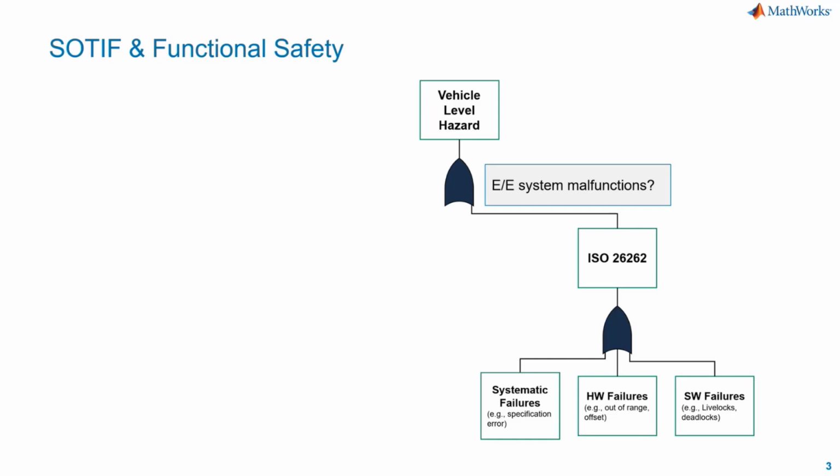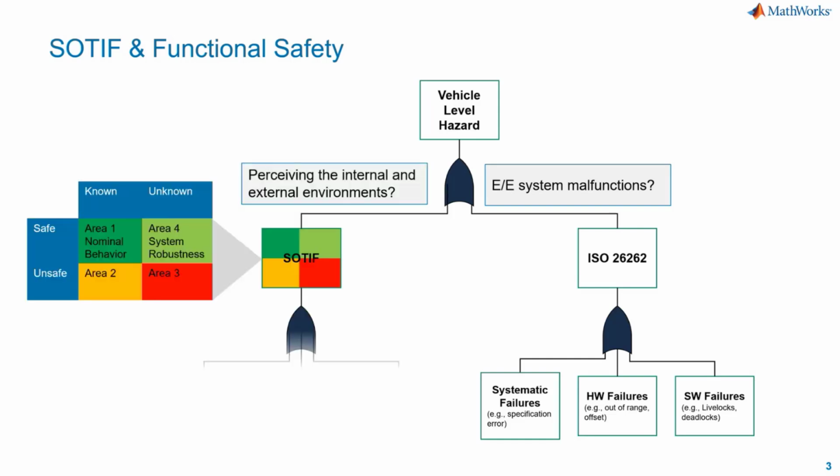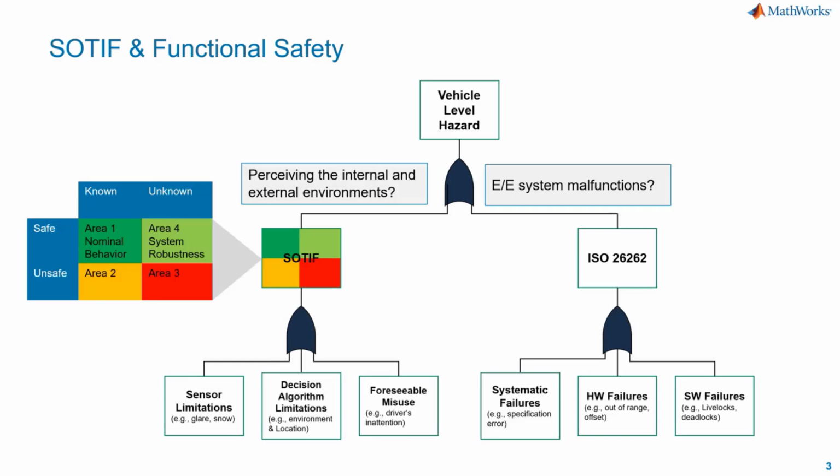But specifically for ADAS and AD, this ISO 26262 standard might not be capable of handling all these hazards because of limitations of perhaps the sensors or the algorithms. That's why we have the SOTIF standard as a kind of compensation in terms of functional safety.